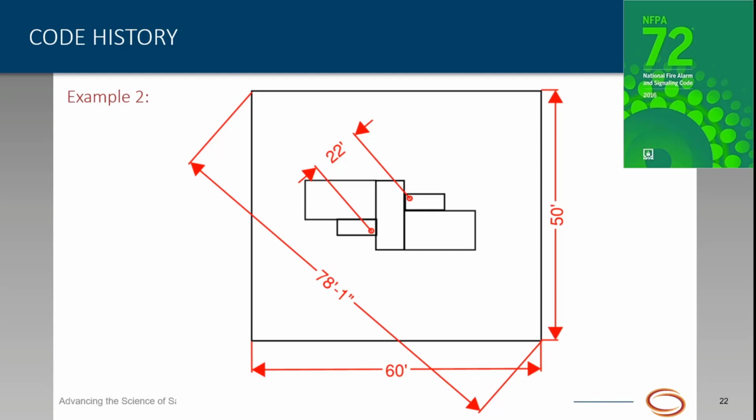Now, if we place a Class X or Class N riser in each of those common electrical rooms, it would only give us a separation of about 22 feet. So we would not meet the needed exception in 72, and thus survivable cable would be required, assuming the common electrical rooms were not 2-hour rated, although that would be an option to also meet the requirement.